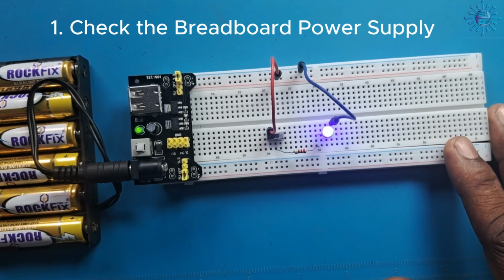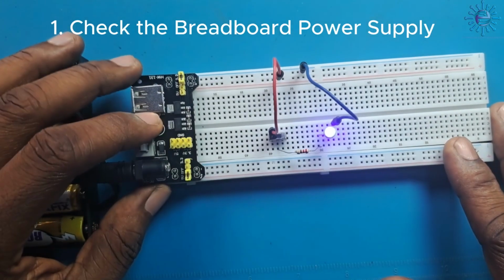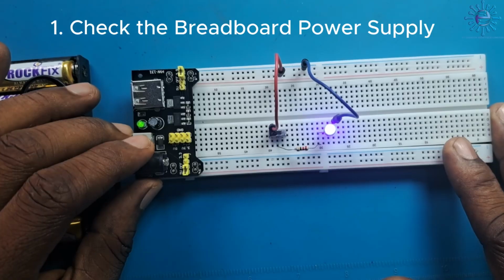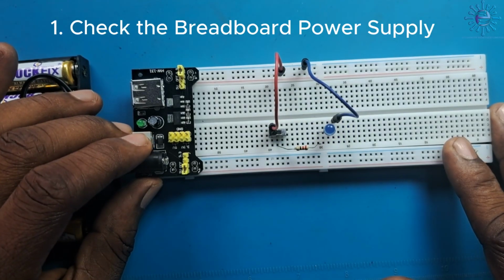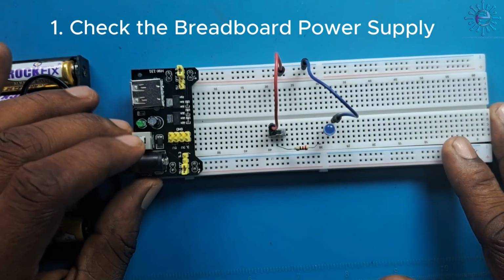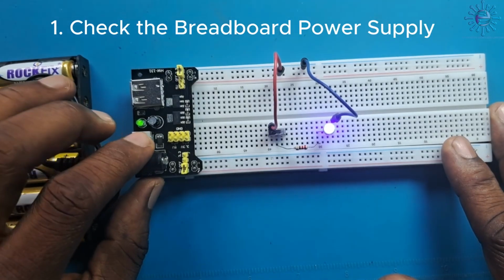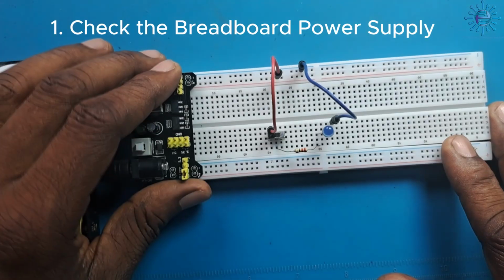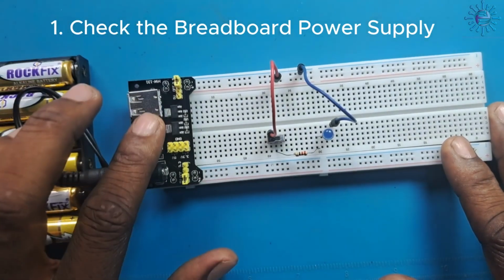Check the breadboard power supply. Make sure the power supply module is switched on. If it is turned off, power will not be supplied to the circuit. As you can see here now, it is on, but if it is off, there will be no power supply to the circuit. So make sure to check the breadboard power supply.